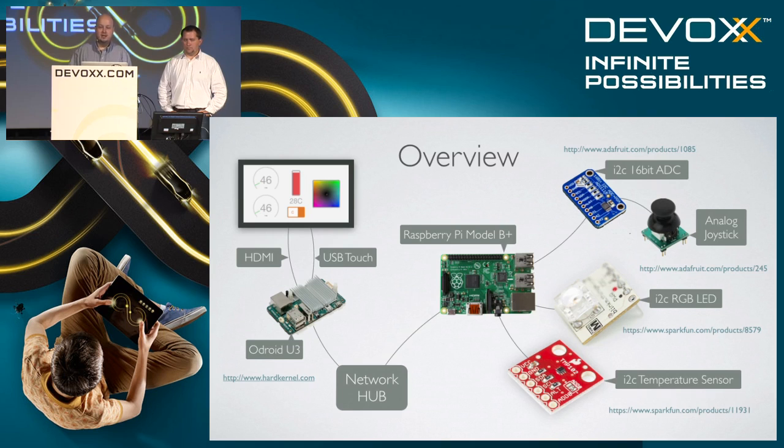Then we have three different hardware interface boards coming off that, all connected via the I2C bus. We have an analog to digital converter, which is reading a little joystick. This is basically exactly the same as we did for the pedals. The two pedals we use on the demo are actually musicians' pedals for keyboards, but they just give us an analog signal.